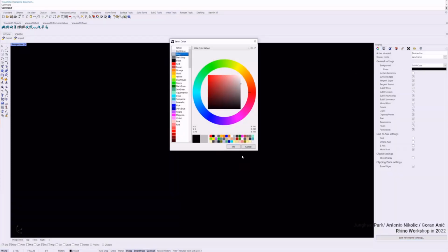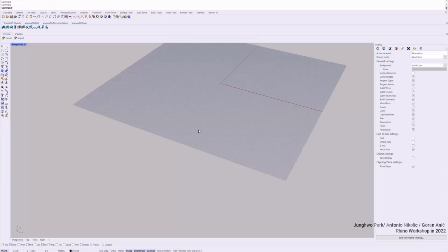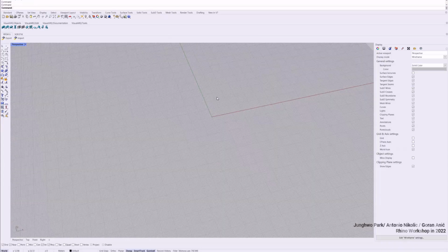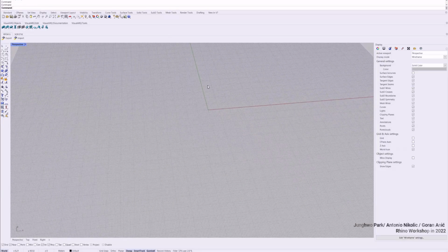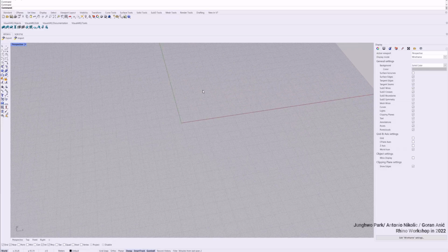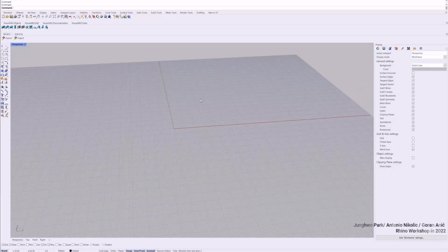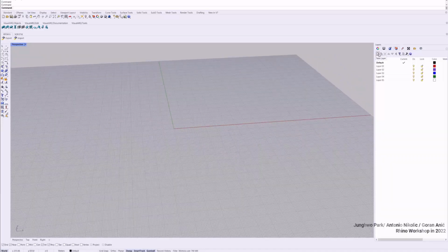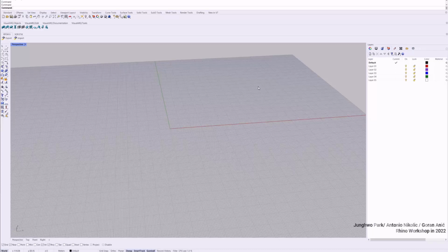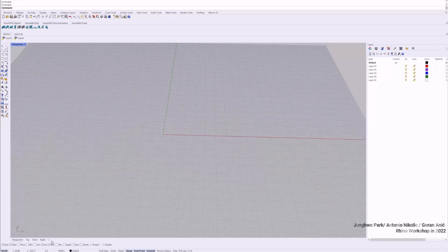That's good. So last week we were doing a little bit of 2D tools using hatches and line weight printing PDF, and we also talked about sections, how to draw a section in Rhino, and we looked at some extra title block, like the viewport we can add to put the drawings there.